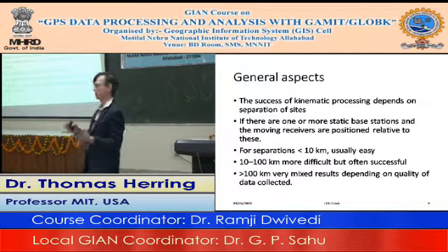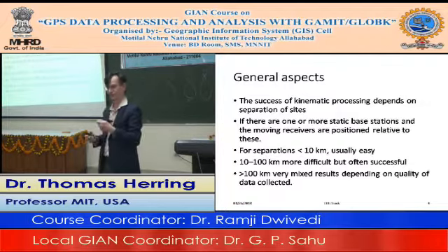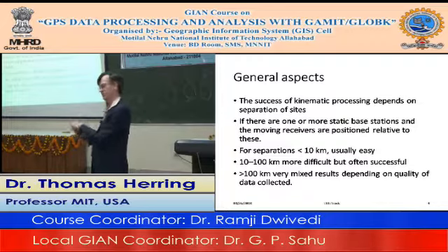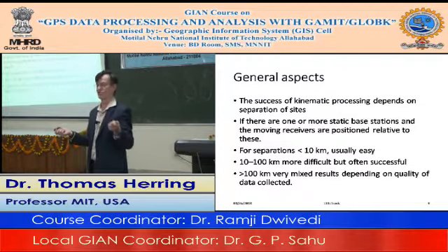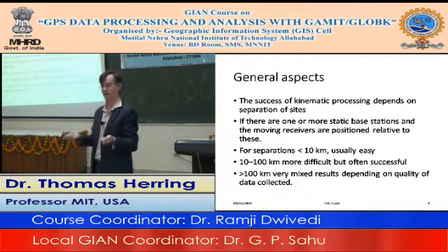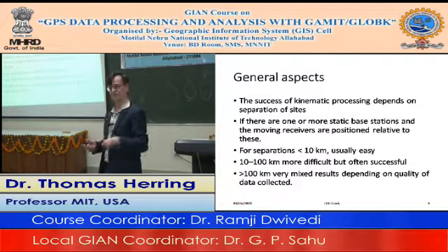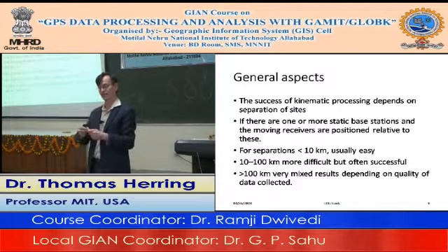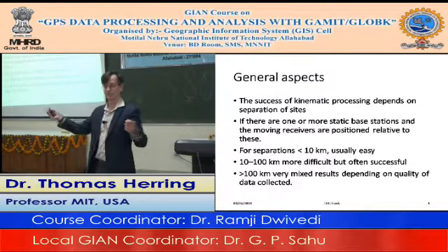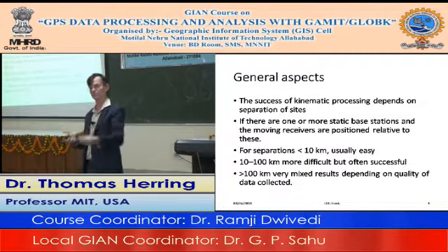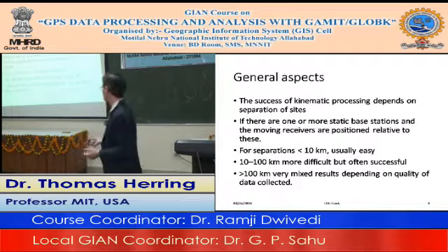And this is particularly problematic if you have an external recorder, where you're spooling the data off to a hard disk, which is often what happens when kinematic receivers are put in aircraft for doing gravity surveys or LiDAR surveys. Because of the volumes of data they're collecting, they spool the data directly onto a hard disk, and in that case, there's often a lot of loss. If you're getting data on a telemetry link, like a real-time stream, then often there is missing data because the telemetry link just can't keep up with the data volumes.